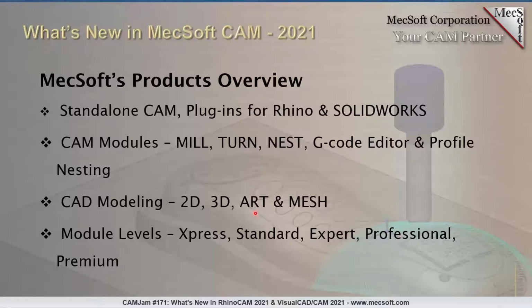Take bitmaps and black and white pictures and convert them to linear or vector art for machining as well, and use it in machining. And then finally, we have the Mesh module that runs both in the VisualCAD/CAM as well as the RhinoCAM product. This is a really interesting module. If you're working with meshes, large point data, and things of that nature, this module would be ideal for you to clean up the data and regularize the meshes, so you have meshes with uniform triangles, and that would be worth a look as well.